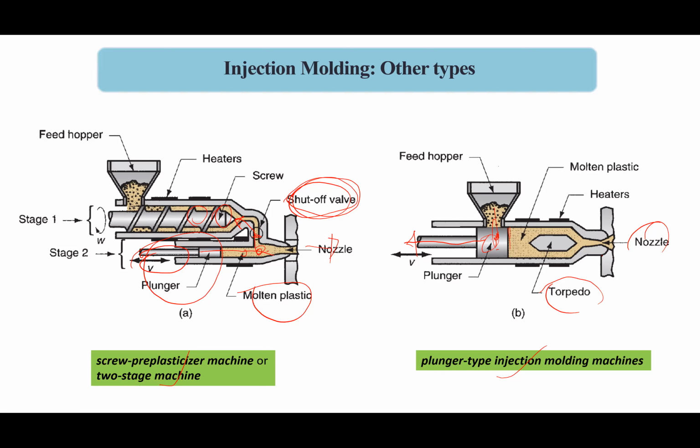No. In the mold, if you have a mold, it is something like that. This is the cavity, and there's a parting line, where this is the movable platen and this is the fixed platen. When the movable platen is fixed with the fixed platen, there will be no air gap. But similar to the screw I discussed, there are some vents of 0.01 millimeter diameter. A similar type of vent is also available in the mold to remove the air.